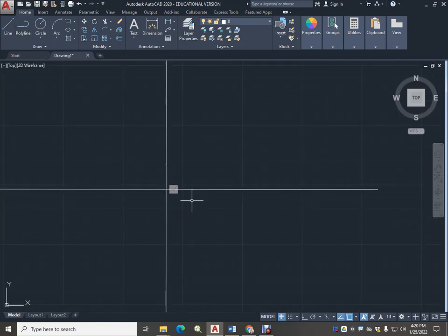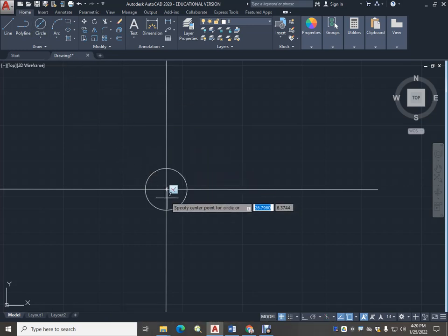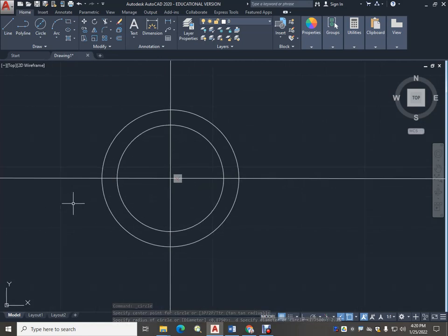So the first two pieces that I want, we'll start with some circles. I'm going to start with two diameters right here in this corner, and 1.75 is the first diameter, and the second diameter is 2.25. Now we've made something similar to this. It's like the gas cap on your car that has anywhere from 4 to 6 prongs that you insert and then give it a half turn or quarter turn and it locks in. So we're going to do these, and these tabs are set off at a 30-degree angle.